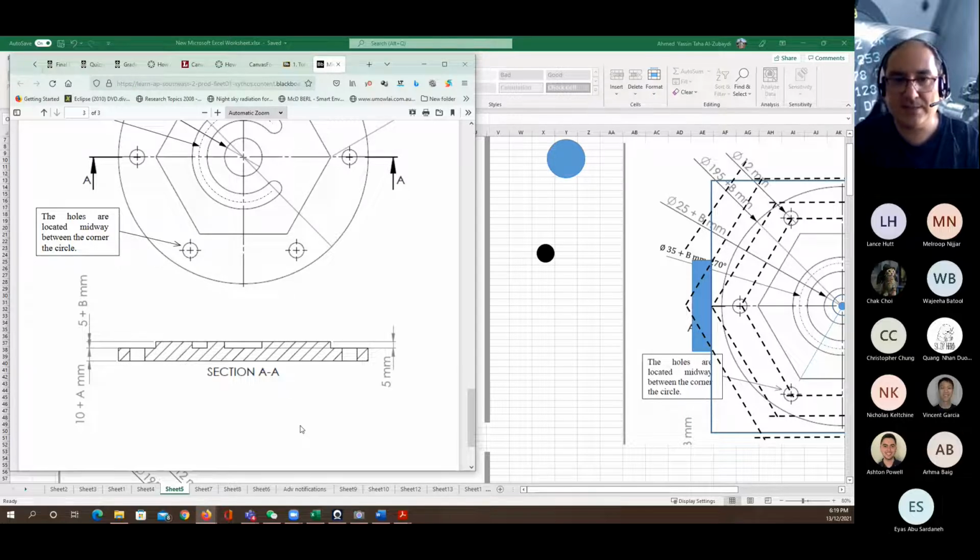So the S is going to be low, the F is going to be high, and the depth of cut, or the Z value in negative, is going to be high, maximum 2. And when I'm going to do the finish cutting, I'm going to reduce the depth of the cut to 1 millimeter, for example. The RPM value will be increasing by 150, and finally, the feed rate is going to be slower.